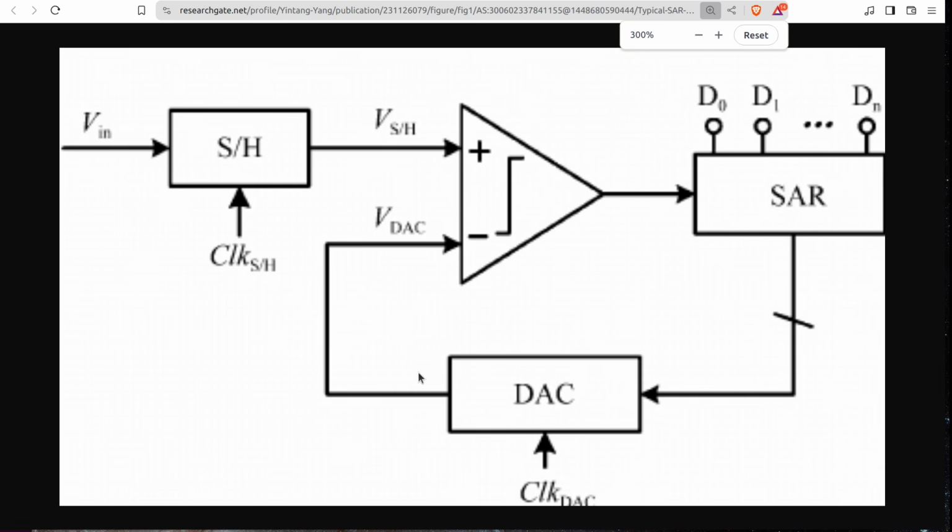Now, I'm a digital boy, and so I jumped in through the question, how do we bring state information from the analog world into our digital machines? The answer to that was my first try at an analog ASIC, and it's a mixed signal design, an ADC that touches a voltage in the world with an analog front end and then uses logic to translate it to an 8-bit number that can be used in compute. Because a big part of this process is manual and one way, it's pretty annoying to change a layout once it's done. It's a great idea to sit down and have a hard think about the requirements and objectives to come up with precise goals and specifications before you start. That is smart and not at all what I did.